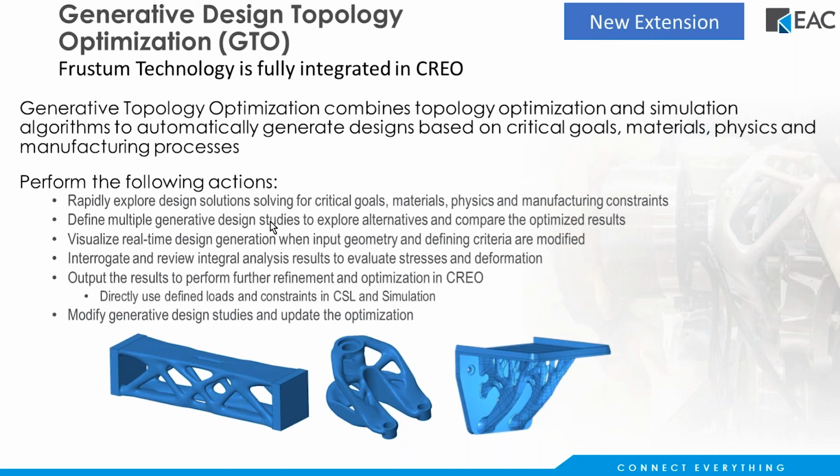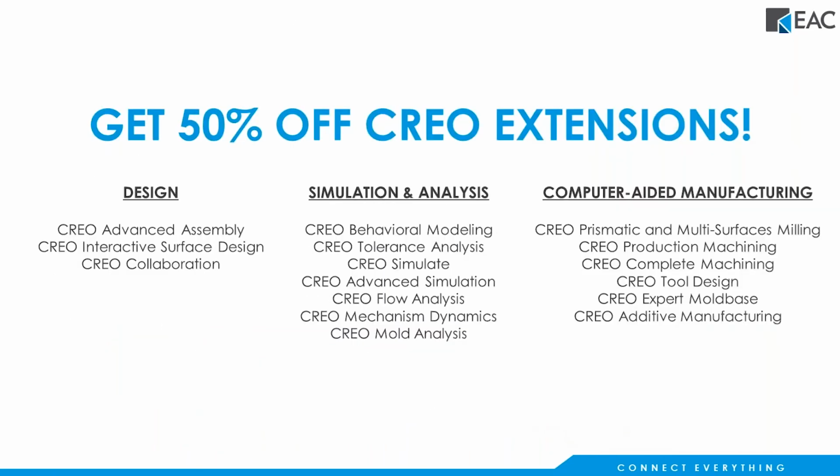I want you to remove as much material as possible, but I want to be able to cast this, or I want to be able to manufacture it, or I want to make it in a 3D printer, right? So it'll put all kinds of holes and squirrely pockets in there that you couldn't make with a mold or a casting or machining, but you can make on a printer. So again, it removes as much material as possible, making your parts lightweight, but still taking into account the capabilities that you want for the part to be able to work with.